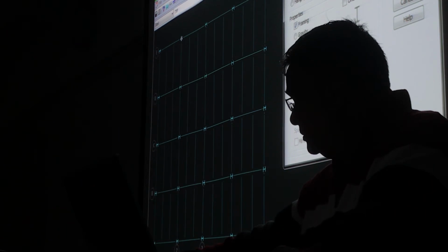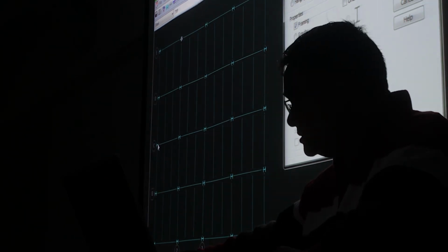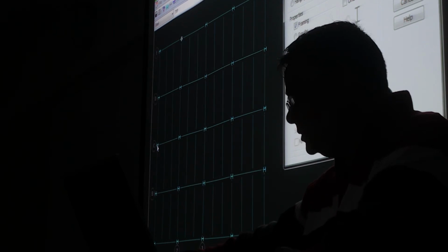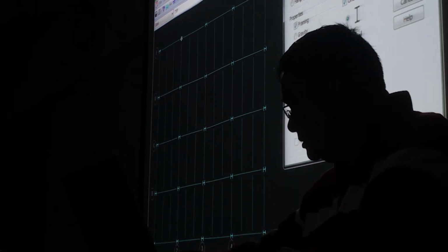Are you with me? Yes. Okay. Another thing is, if I'm saying that framing is in this direction, look at the column orientation. It is connected with the weak axis, right? I want to get the maximum possible stiffness in that direction. So I'm going to change the direction, which is orientation, and I'm going to make it like that. You follow me? That answers your question.